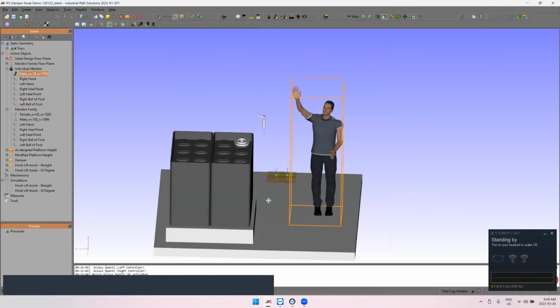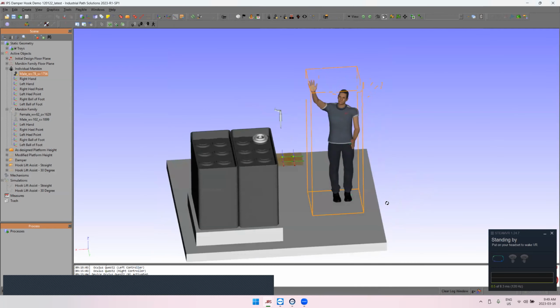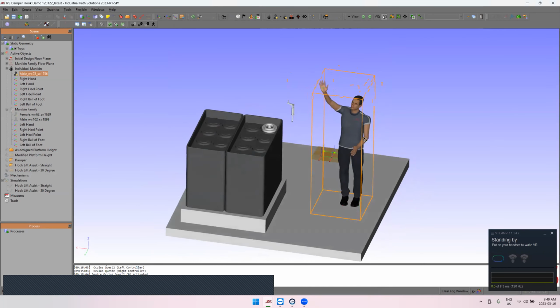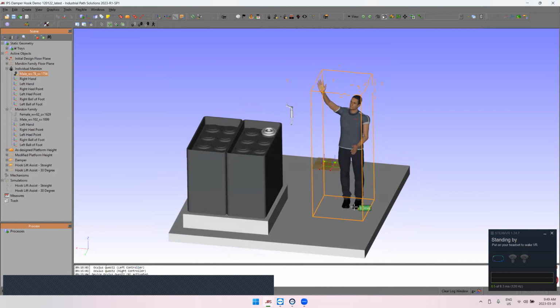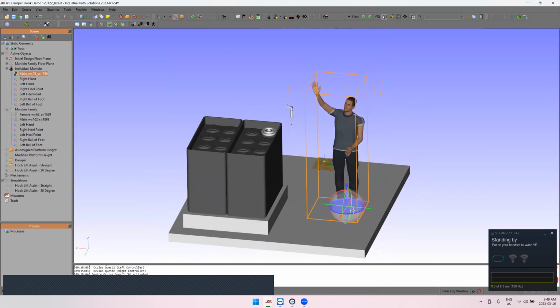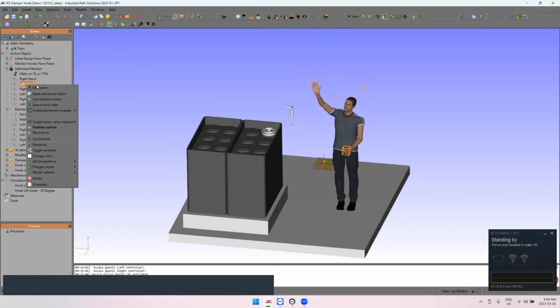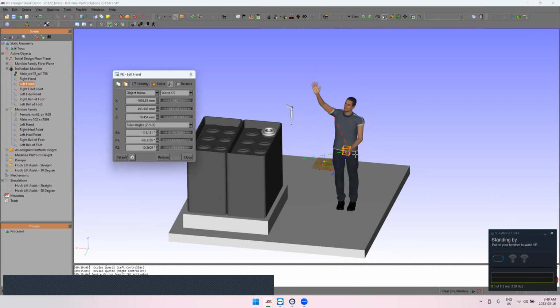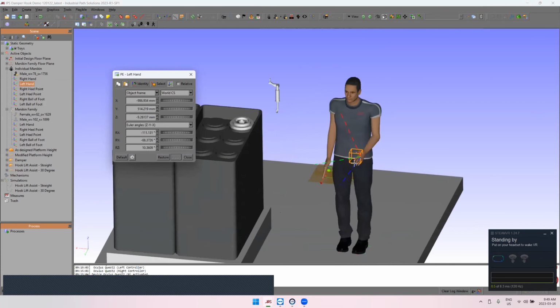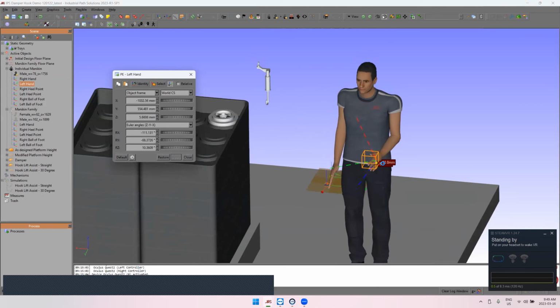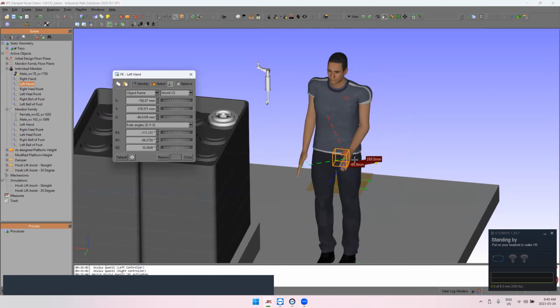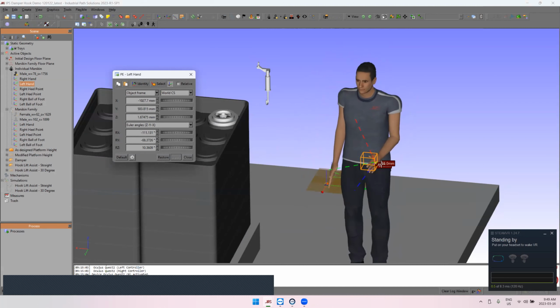With regards to our IMA mannequin that we're showing here, we can manipulate this in a bunch of different ways. We can just move where it's located in the scene by moving it around. We can also choose to move individual components of the mannequin by opening up the placement editor, and we can move individual components of the body around. As I'm moving my mannequin around, or just the hand, the mannequin is following that hand and attempting to posture based on the goal.